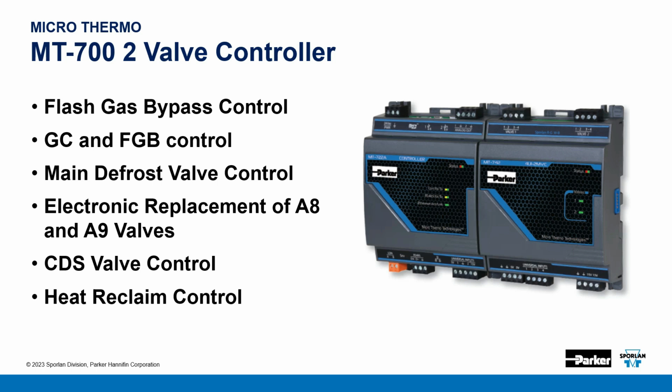You can take a Parker A8, A9, turn it into an electronic valve, and we can control and monitor the A8 and A9 valves as we turn them into an electronic stepper valve. We can also control the Sporlan CDS valves, and we can also do heat reclaim.